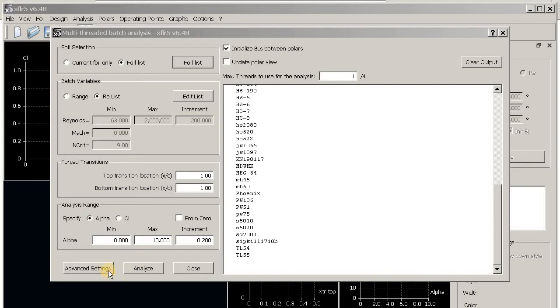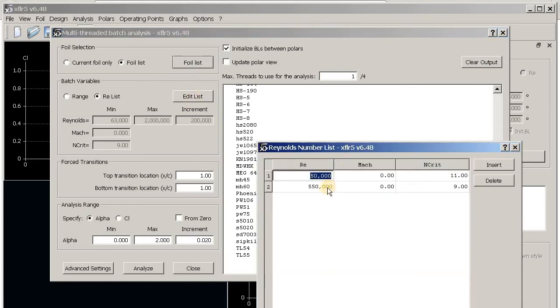And the final thing is to choose the alpha range. So for the high speed, I'm going to use a small range. I think 2 degrees is going to be sufficient for the high speed. I'm going to make small steps. 0.01, 0.02. Okay. And yes, we have to change this because I'm going to use a different range of alphas for the low and high speed.